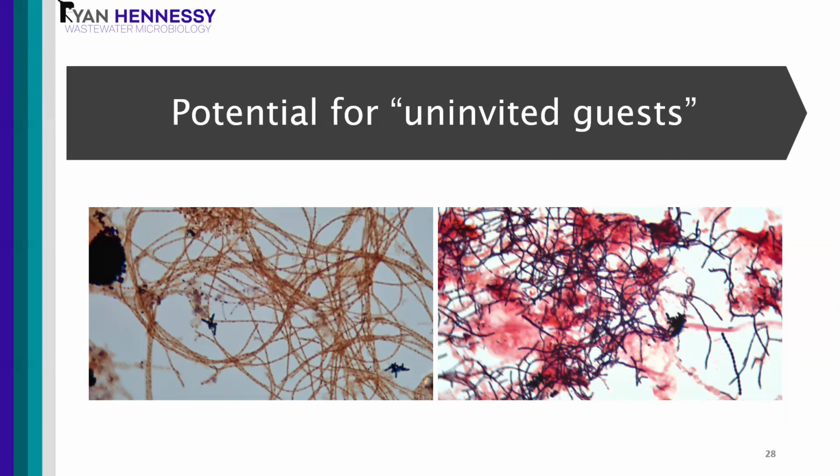So it's common in some situations that if a plant implements a selector zone and goes to biological phosphorus removal, even if the FOG, fats, oils, and grease, stays the same, now that you've introduced the septicity, that can promote certain filaments. There are some filaments that do compete very well in the selector. Your anaerobic selector in general is going to select for good bacteria, but there are some uninvited guests that it has the potential to help select for.